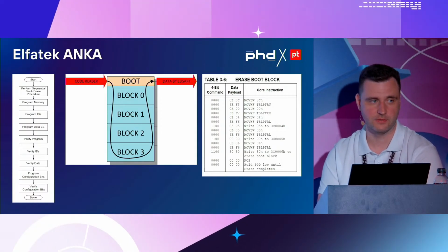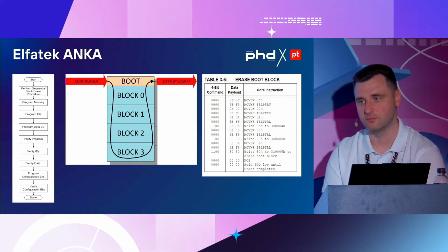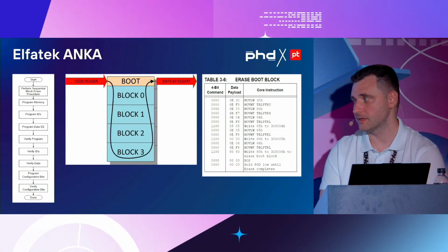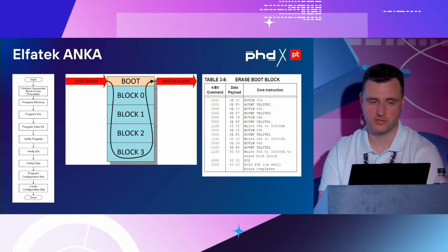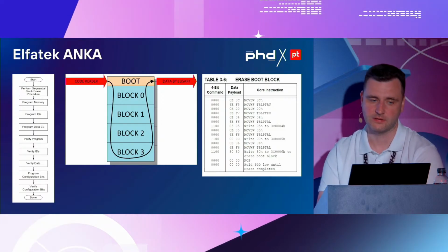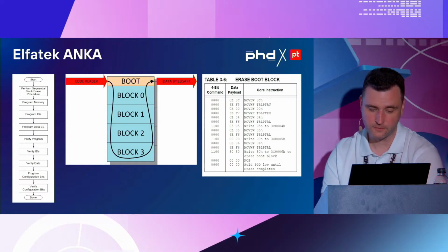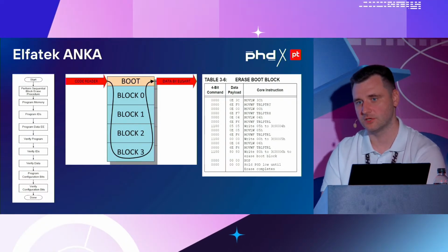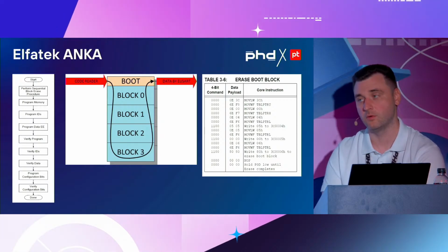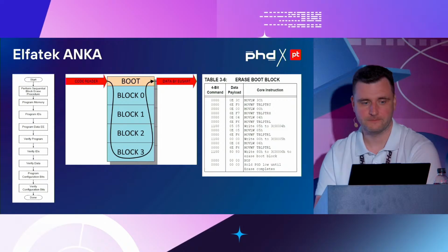So then we made our own BitBang program in order to erase the BootBlock. It works very well on the pilot chips and doesn't work on the target one. Then we started figuring it out. It turns out that a certain bit configuration and pin configuration sets the programming mode, and it is high voltage. It means that it has to be supplied with 9 volts.